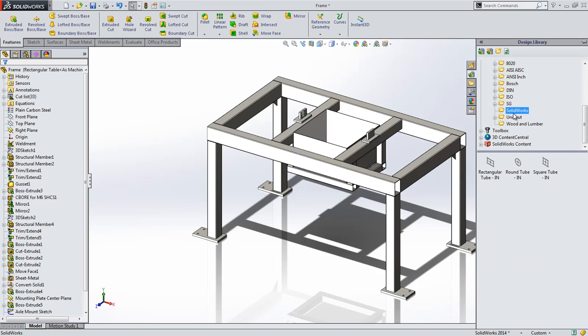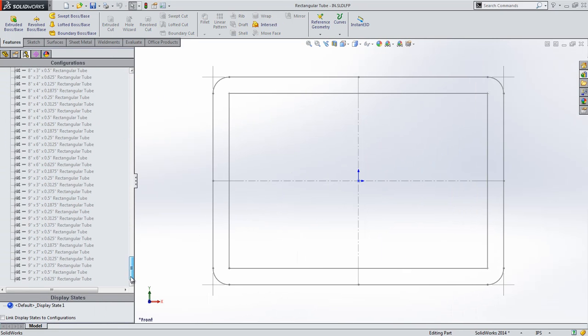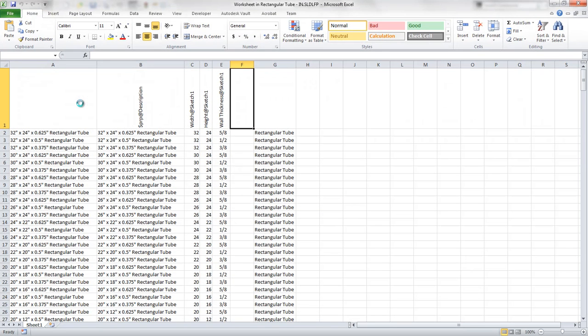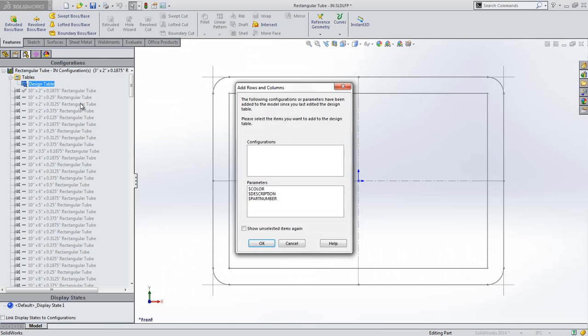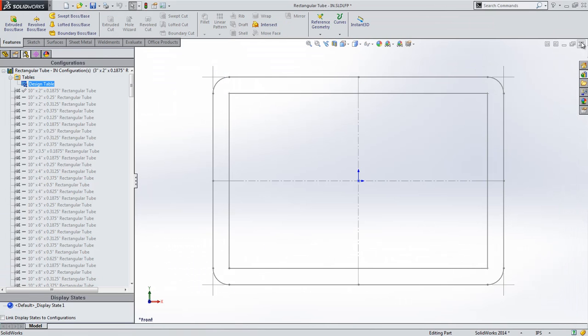unique sizes. Now, instead of subfolders for type, there are simply single files for each type of profile. If we open one of these files, we can see the file is populated with a vast amount of profiles to choose, all from within a single file. To further benefit from this, all of these profiles can be created and maintained using powerful design tables to rapidly create all of the different sizes. This is done leveraging simple Microsoft Excel concatenation and speeds up the entire process of creation drastically.